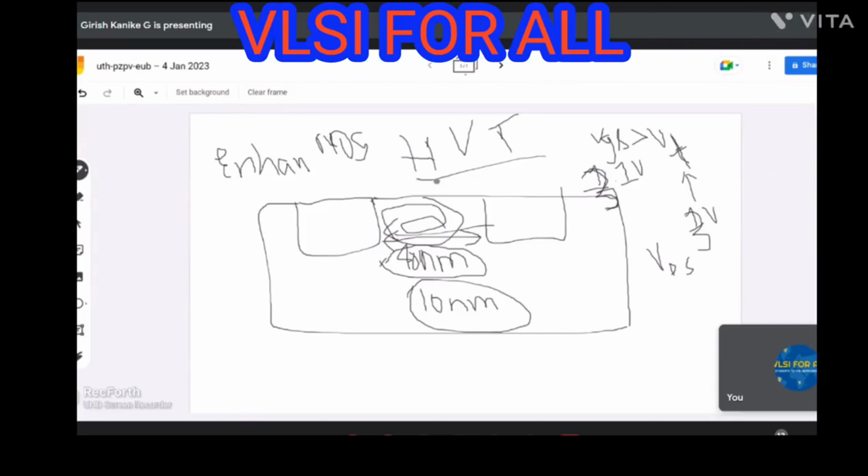Why? Again, you need to go with the basics of CMOS. I'm not going to touch that. Technology-wise, if you go with HVT or LVT, you can't achieve it at certain nanometer technology. For example, you can't achieve it on 180 nanometer technology. So you don't have HVT or LVT in 180 nanometer technology or some other technology. These HVT and LVT come into action in some nanometer technologies.